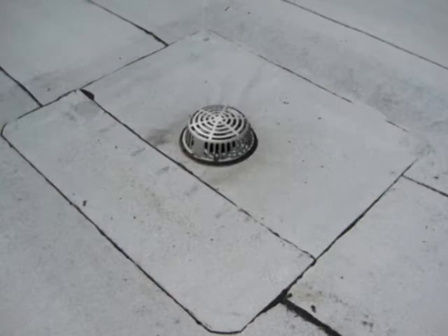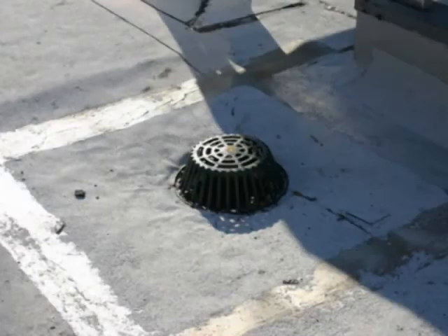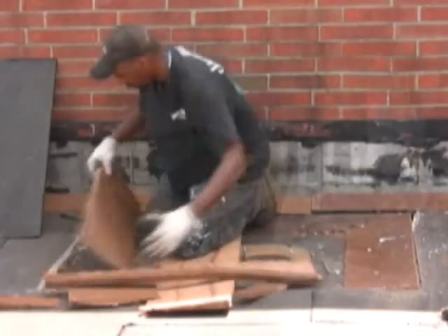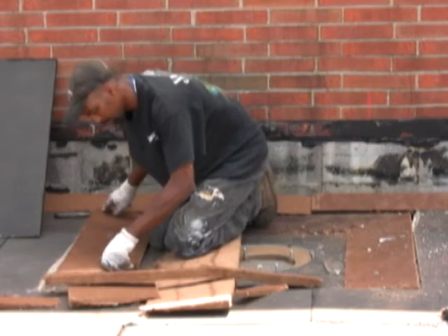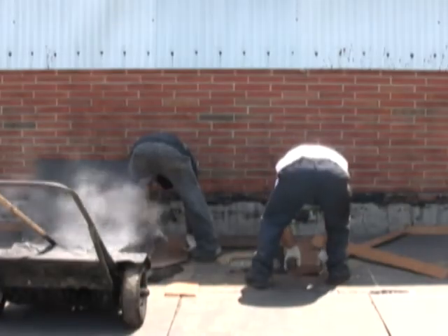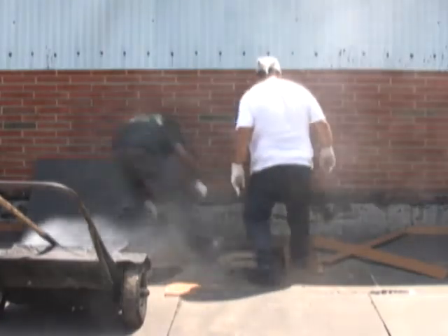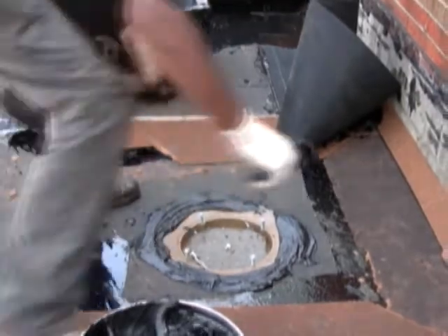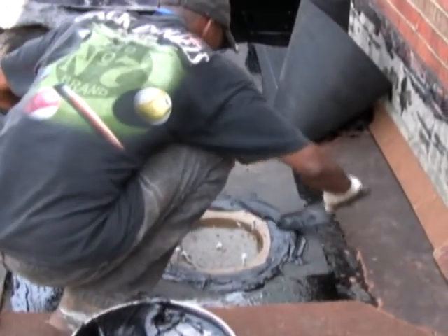Typical waterproofing of a new or existing internal roof drain includes the following steps. Plug drain to prevent debris from entering plumbing. For projects that include insulation, insulation should be tapered to drain a minimum of 24 inches from the center of the drain. This process is also known as sumping the drain and serves to increase the flow of water to the drain and off the field of the roofing system.